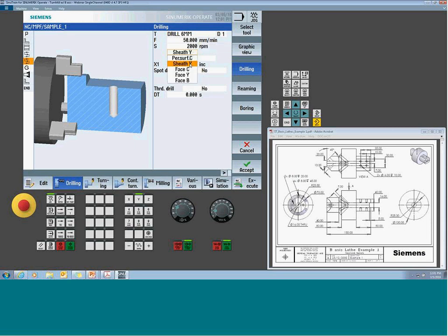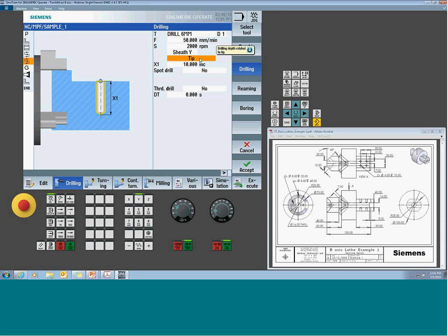Now, do I want to position with the Y-axis, or do I want to position with the C? In my case, I have holes that are off-center, right? They're offset to the center line, so I have to position in Y. And just remember this option, because it's important to reflect this when we get to the position screen.